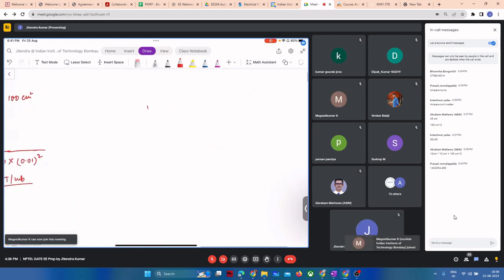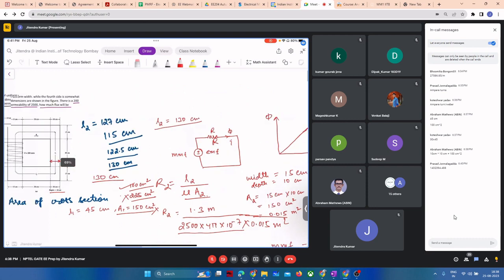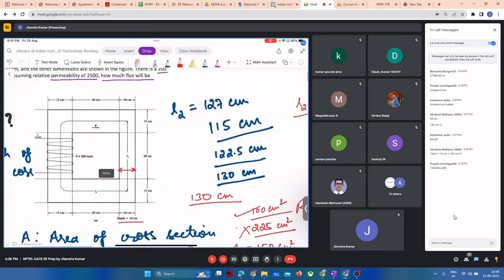Since we know the magnetic equivalent circuit, we have the MMF and we have the reluctances. Since we have computed two different reluctances, should they be connected in series or parallel? If parallel, why?